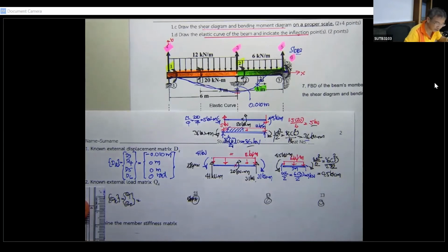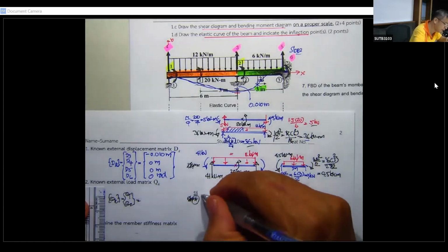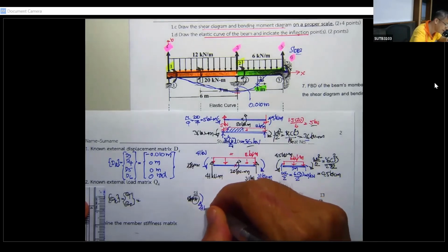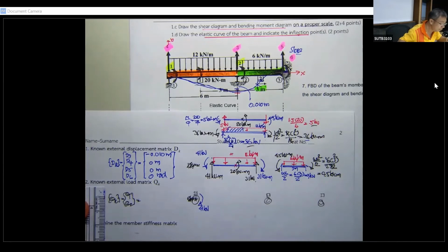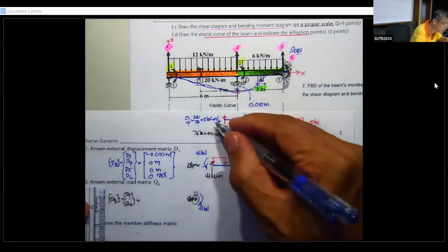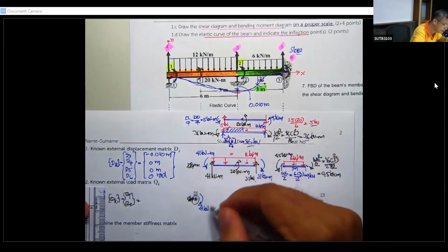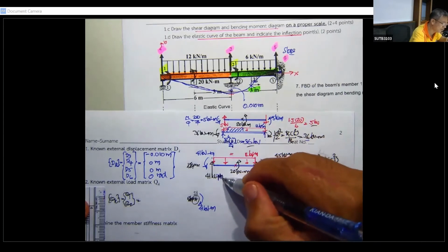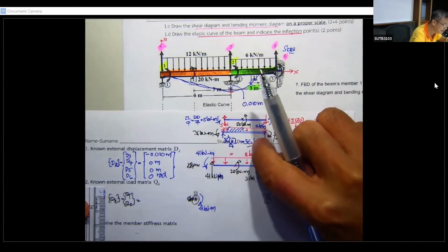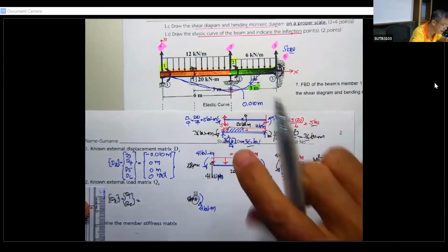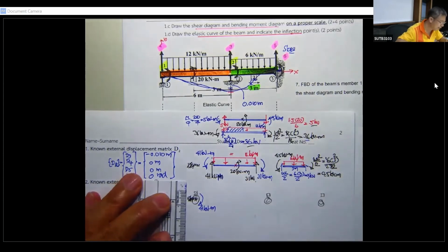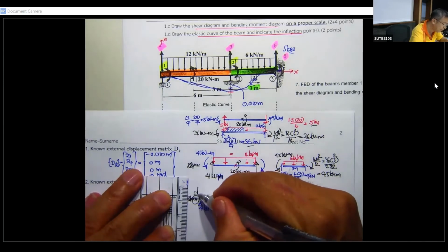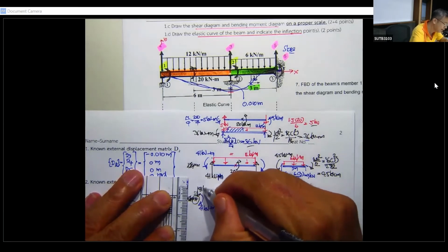And then you just make the reverse of the fixed end shear and fixed end moment by using the third law of Newton. This is going to be 41 kilonewton meter, and this is not correct. I did this wrong. Okay, 5 and 36, that is going to be the 41 kilonewton. So this one will have 41 kilonewton.